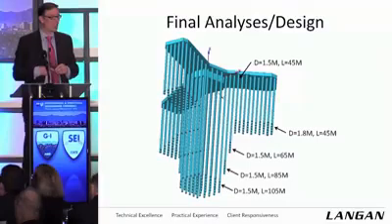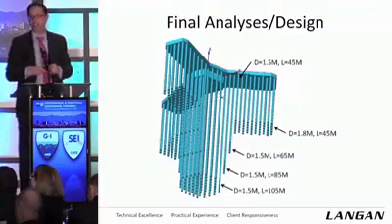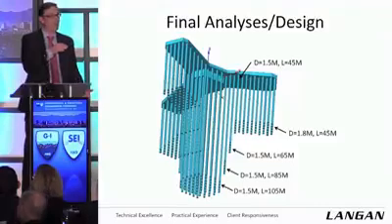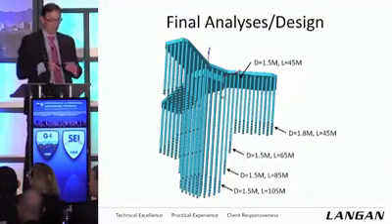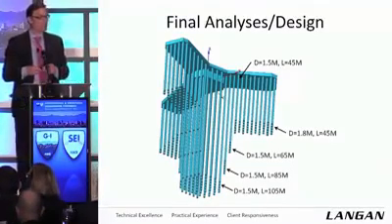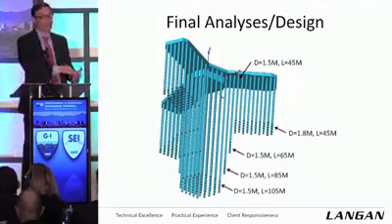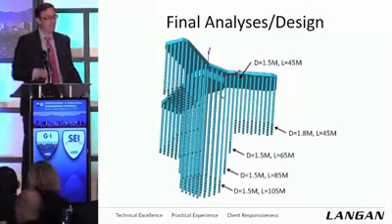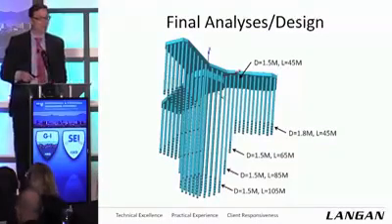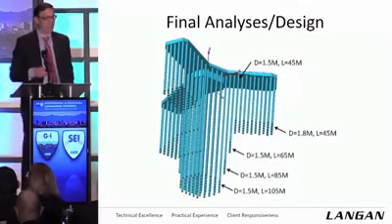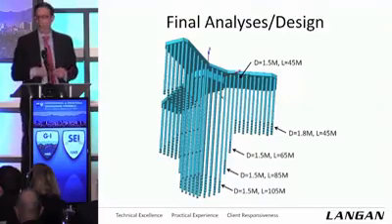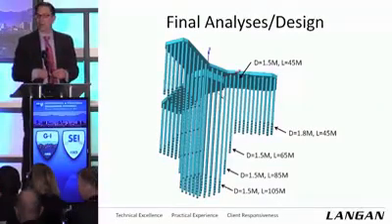So they ended up as 105 meters in total length, and we wanted to stay above that competent sandstone at depth. We didn't want to have hard points at the center of the tower, so we chose 10 meters above that to give ourselves a nice cushion, and then we stepped it up at 2 intervals, 85 meters and 65 meters. And then we kept as many piles as we could at 45 meters. We still had this gravel zone, and if we didn't have to penetrate it, we didn't want to.